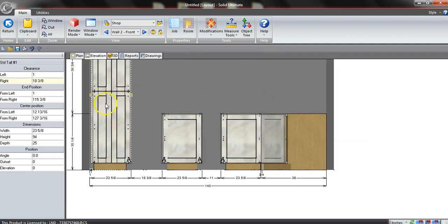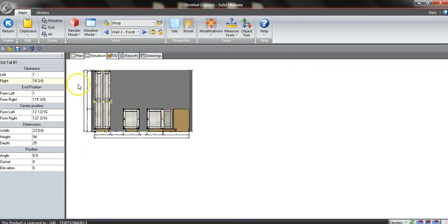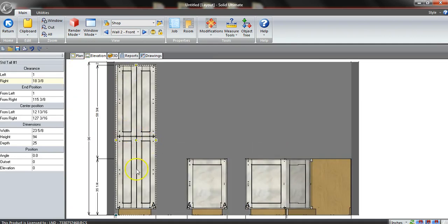And then we're going to turn this guy here into a fridge cabinet, okay? Fridge 36 usually, so make this 40. And this is the hardest cabinet in the whole thing because Cabinet Vision doesn't have a face frame fridge box, so we kind of got to create one.